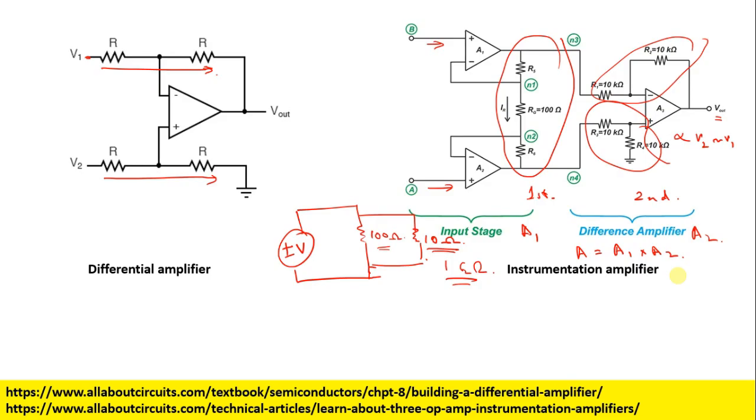And I also asked about the common mode rejection ratio. What is common mode rejection ratio? It can be found for any differential amplifier, where we are basically giving differential inputs. First we give a common mode input. Common mode input means the same input. For example, if I give 1 millivolt to both the terminals, ideally we should not get any output, because our output is directly proportional to V2 minus V1. So ideally it should be 0.